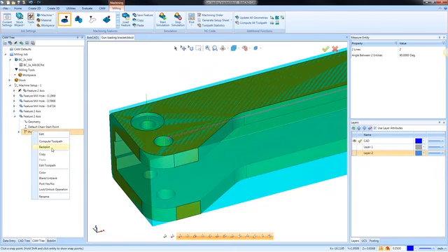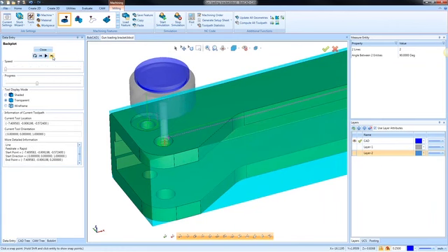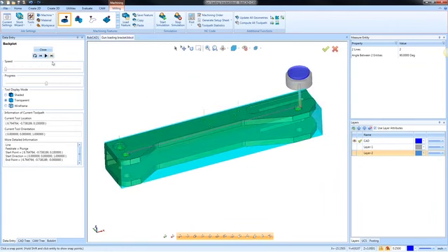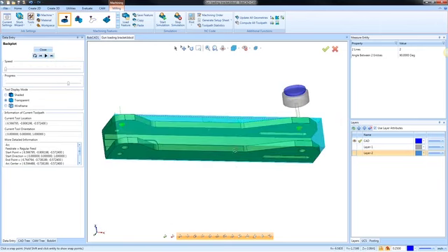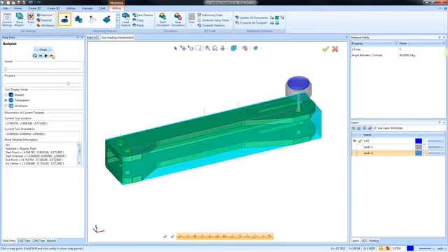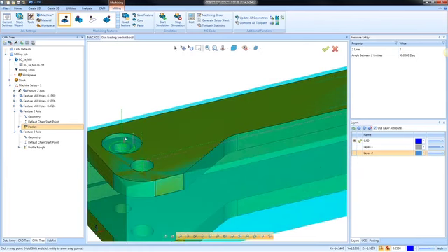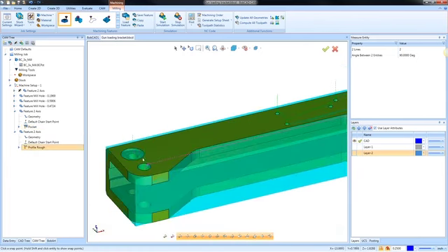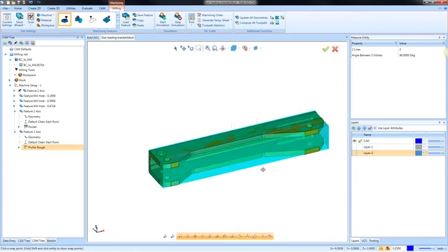So what that will do is just increase the tool size. This one here, I'm going to backplot again, and you'll see that this circular interpolates, gets down to the bottom, comes back out, works over to the other side, and will continue down to the bottom. You can see the punch through, and then once it's done, it will come back out. Okay, so for this one here, we used a spiral pocket in order to do our counterbore. This one here, we're doing some helical milling in order to clean up these holes.